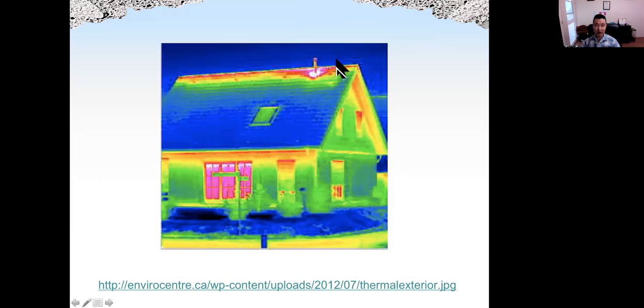Because if you have a leakage, that area will have a higher temperature, which can easily be detected by the thermal camera. And also around windows, you can see here, heat is also going out of the house from the windows and certain areas of the roof. So we know how we can further insulate the house.